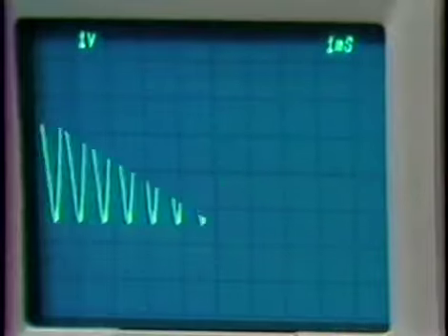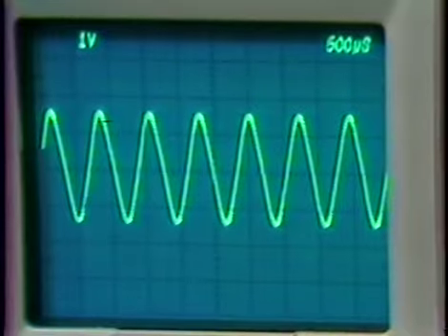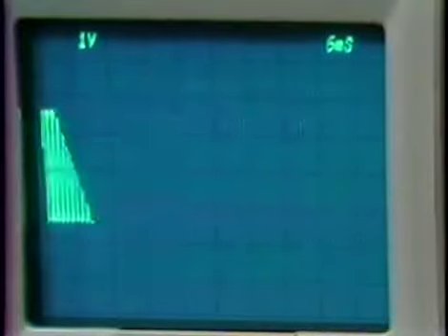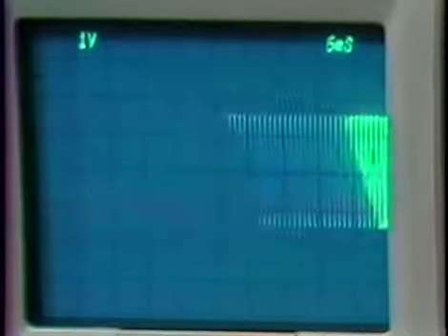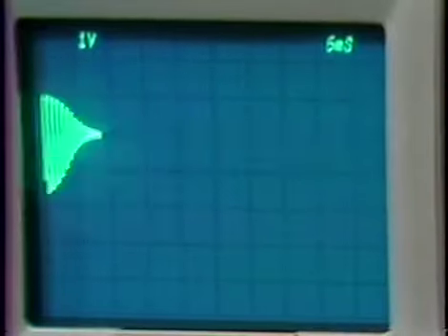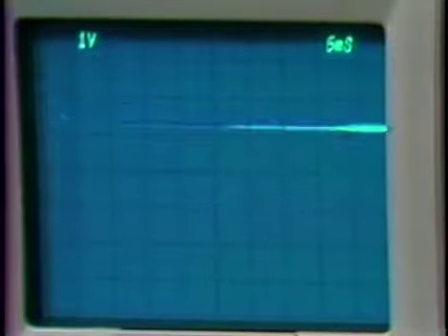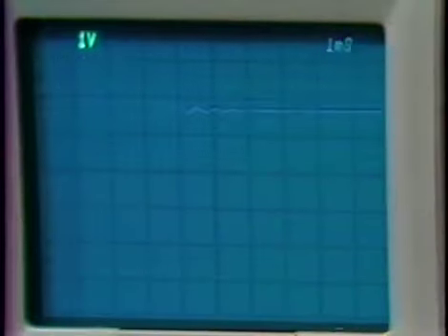And in fact, we can look at the frequency of oscillation, and we notice that it's out around a kilohertz. We're now oscillating at the higher frequency point. In this case, we can cure the oscillation, make it go away, by putting in a large signal. That gets the gain of our describing function element to be higher, and that cures the oscillation. So let's go ahead and put in a larger signal. We go from the unstable case to a system with relatively light damping, but stable.